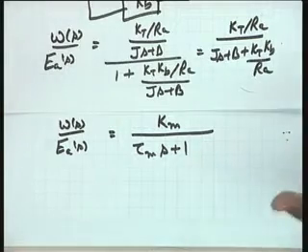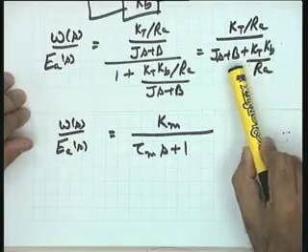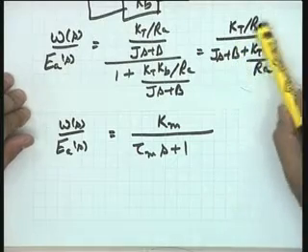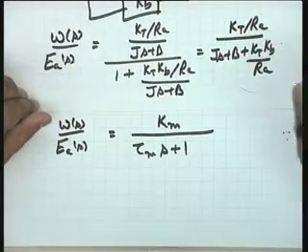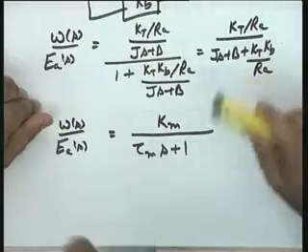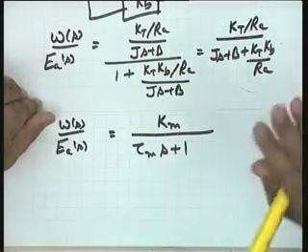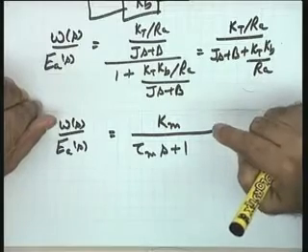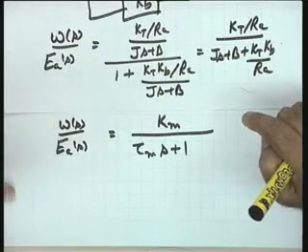Now, I want your comment on the effect of Kb, the inherent damping characteristics of the motor. You will please note that Kb increases the value of B, and hence it increases the effective damping of the motor. So, it is because of Kb that the oscillations of the system can be quickly damped out, a feature which will not be available, as you will see, when we come to the field controlled mode.